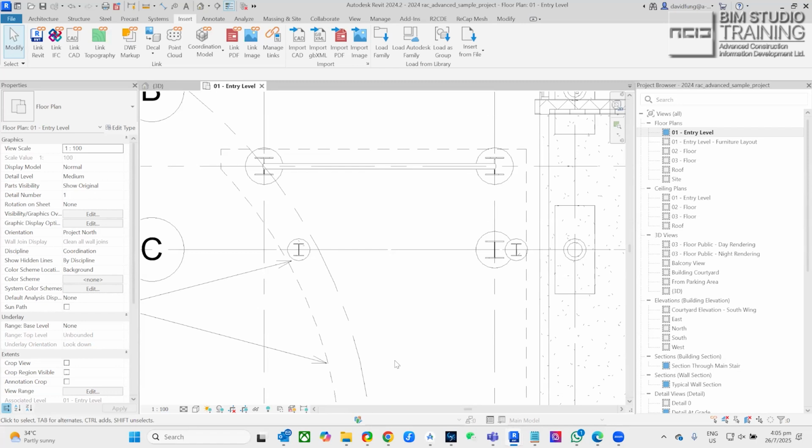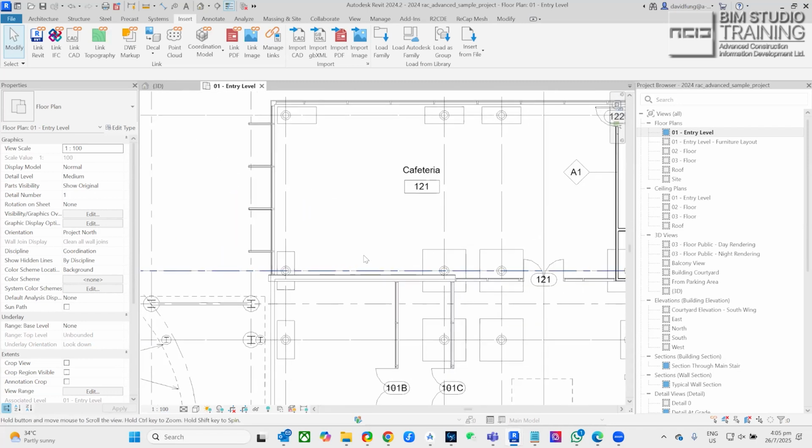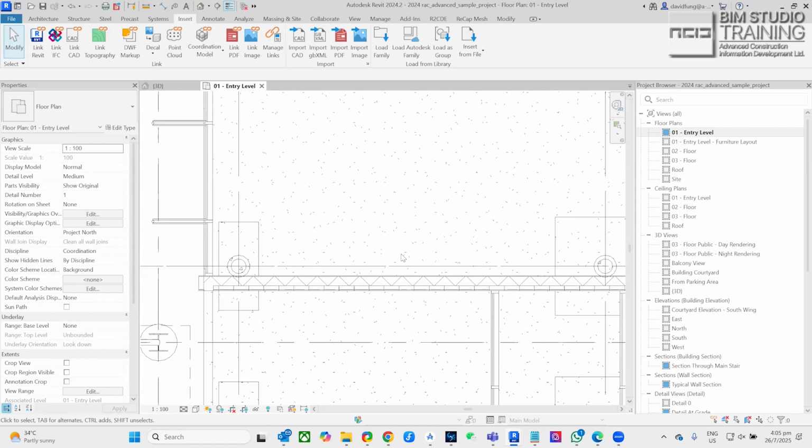All right. Now, let me ask you a question. You can see the difference between architectural design and structural design right now. In number 2, you see there's a clash in here. Why you see there's a clash? Well, I asked you to do that. I asked you to do this. If you do not have my instruction, if you are given 2 drawings, one is architectural, one is structural, you don't know where you cut back. What will you do?